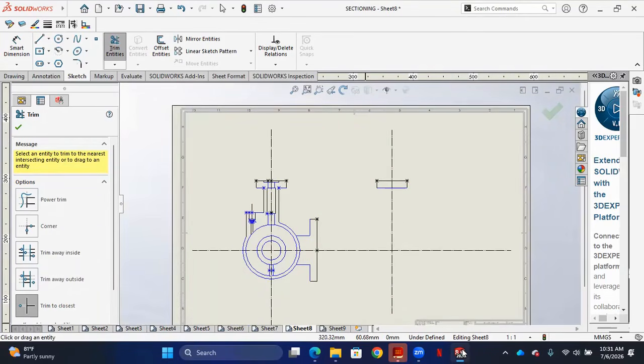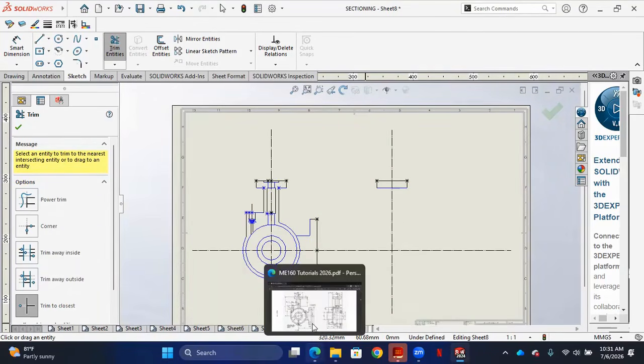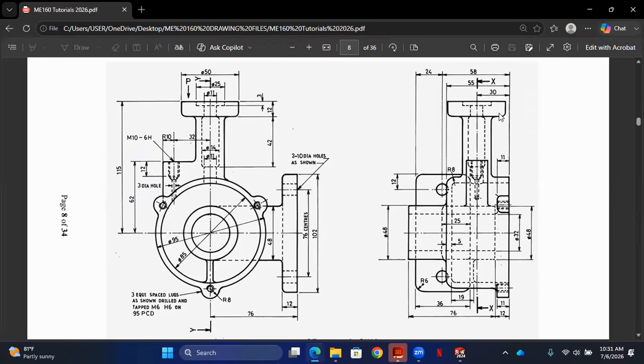Then I come back to my drawing. So now I've drawn this side. I want to draw this side and then this side. It's the same symmetry. I know that between this side is 25, so the same thing, 25. Because you've been inferring a lot from the front view to the side view, I'm going to extend the same thing. So I extend it down.